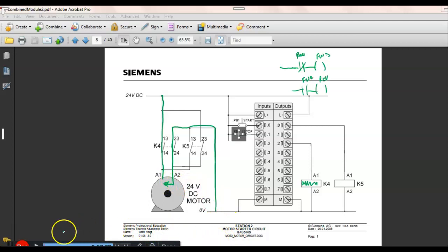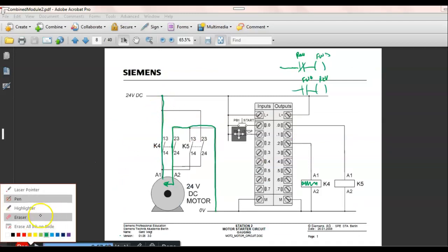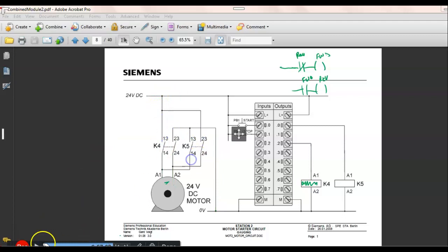So if I come over here and energize K5, okay, here it is. So if I come over and energize K5, so in that example, the current flow was in this direction. Well, if I energize K5, and let's see this in a different color. So K5 is energized, so this contact will close, and this contact will close. So now my minus comes in, okay, comes over here, drops down, comes over here, goes through it in this direction, comes back, and goes back up.